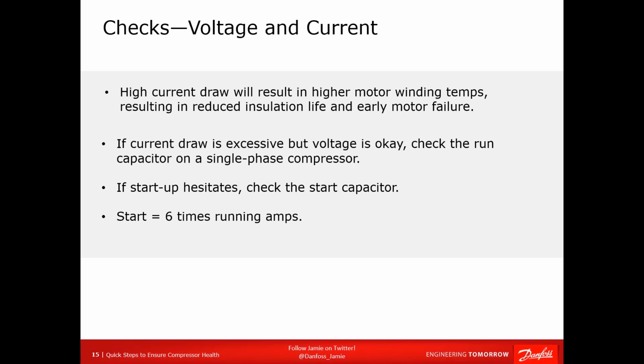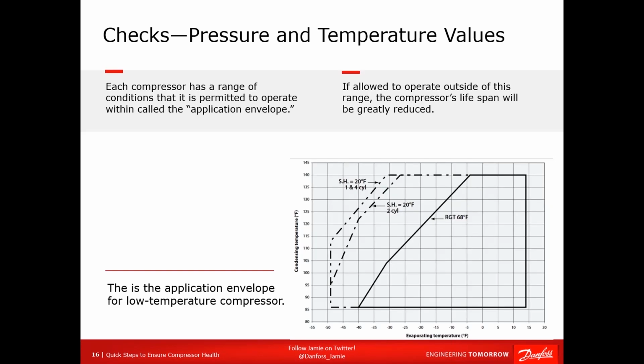And once again, make sure that the compressor starts up immediately. That goes for the fan motors too. They should start immediately. If there's any lag at all, especially if it's clicking the internal overload before it starts, that needs to be addressed. Check the start capacitor, number one. Number two, check the voltage.